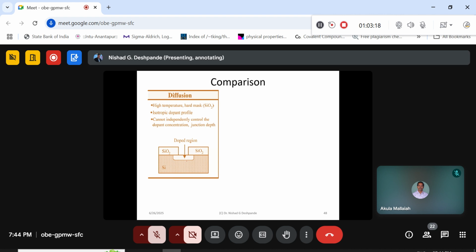This is where one process is possible, wherein you have a heater arrangement so that you use a melting process. The other way is that thermal energy is given to your gas molecules. Note down this is either boron, phosphorus, arsenic, whatever dopant you want, and that will move inside this region. Using the thermal energy, they will move inside and get diffused.